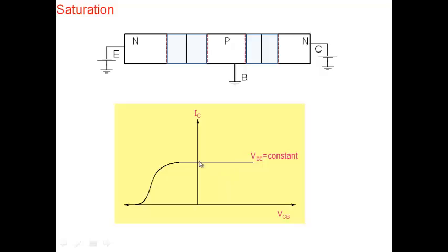The moment I come here, the collector becomes zero biased. There's no bias on the collector. Still, the current is the same. Now when I go on the left side here, the collector voltage has become negative and the junction has become forward biased. But we have just learned that even though you may make a junction forward biased, if the forward bias is 0.1 or 0.2, it doesn't carry that much current. So there's no practical influence initially.